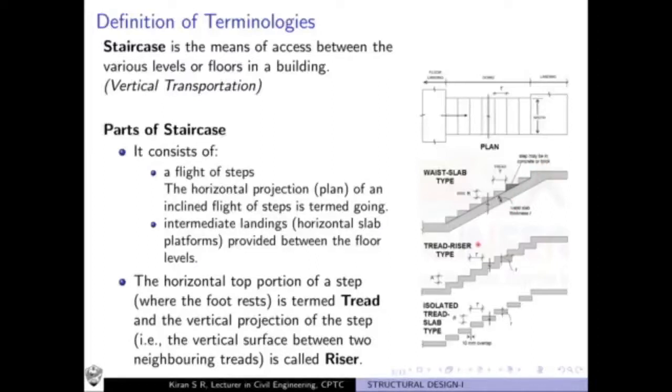Now coming to the tread riser type, here you don't have a waist slab as in the previous case. You merely construct the tread and rise in the form of steps itself using reinforced cement concrete.